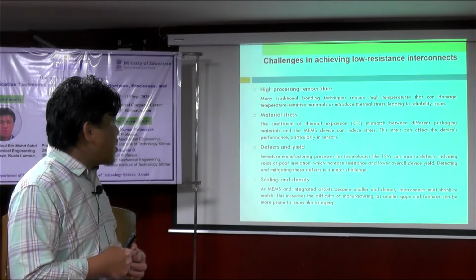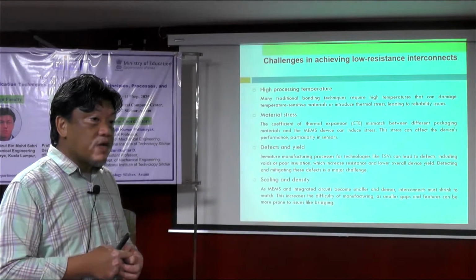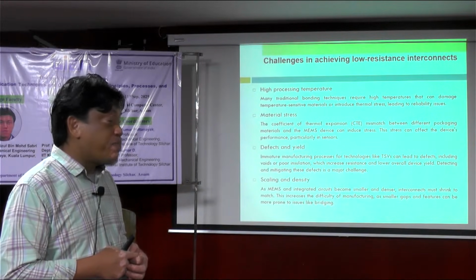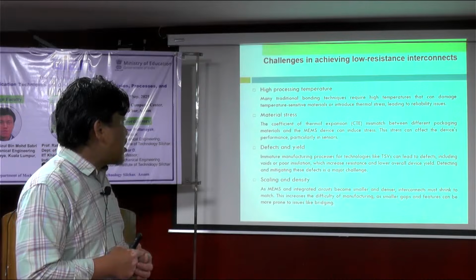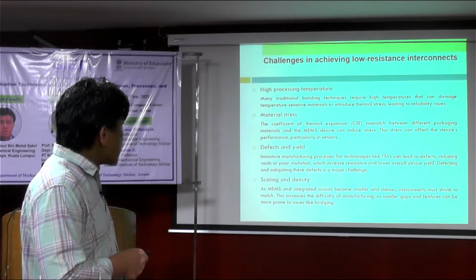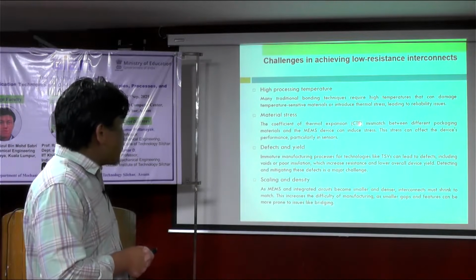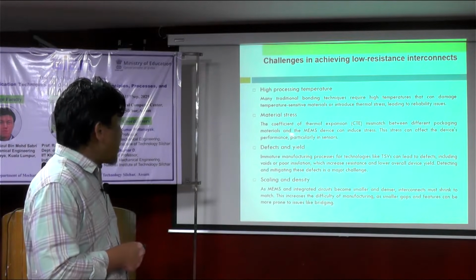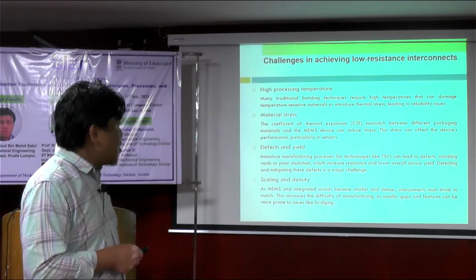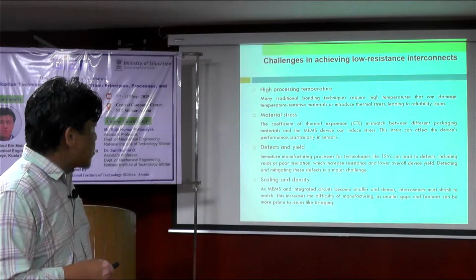And for example, some materials have a low Curie temperature. So such as a piezoelectric, if it's exposed to high temperature, you might lose the piezoelectric property. So material stress, the coefficient of thermal expansion mismatch between different packaging material and the MEMS device can induce stress. So this stress can affect the device performance, particularly in sensors.